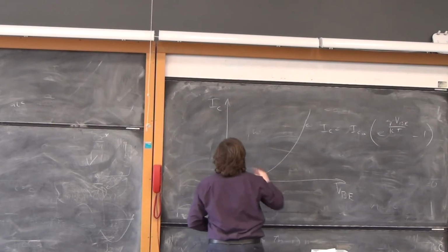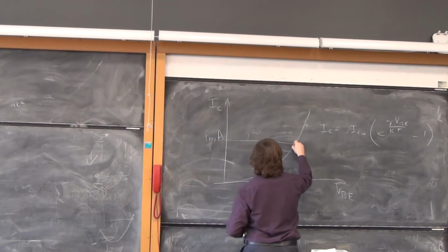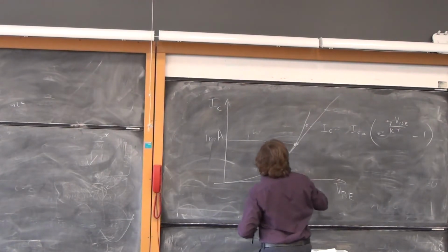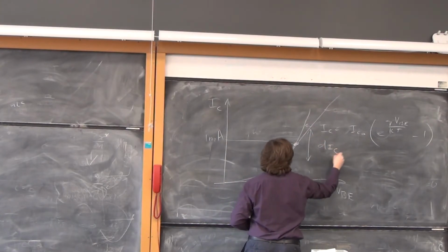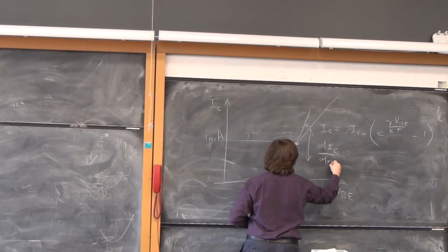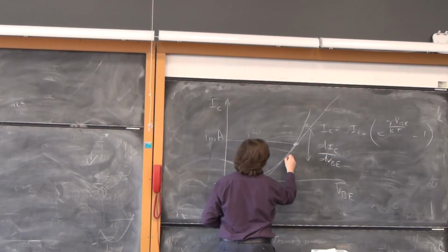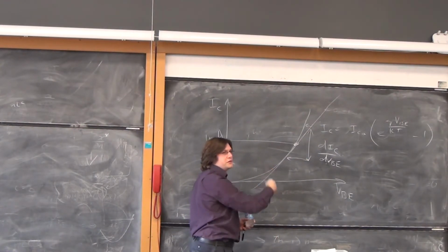And we'd say, alright, well, I'm going to choose a milliamp for the sake of argument, and then I'll be drawing a line up there, and the dIC by dVBE at this point, so drawn across those two, will be my gm.